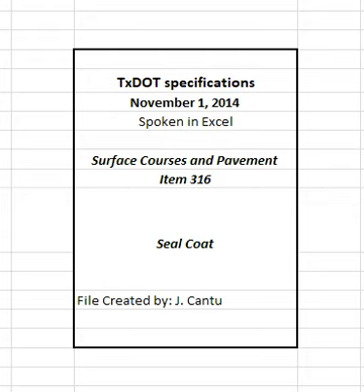Blending temperature, and test results on the properties at reaction times of 60, 90, 240, 360, and 1440 minutes in accordance with Section 300.2.9, asphalt rubber binders. Furnish a new asphalt rubber blend design if the grade or source for any of the components changes.